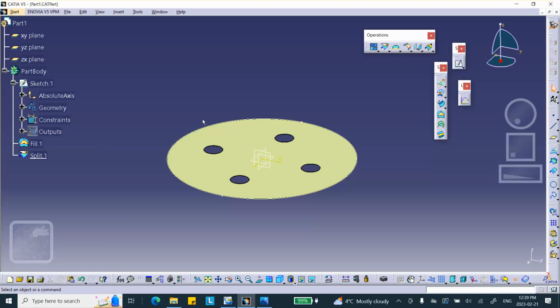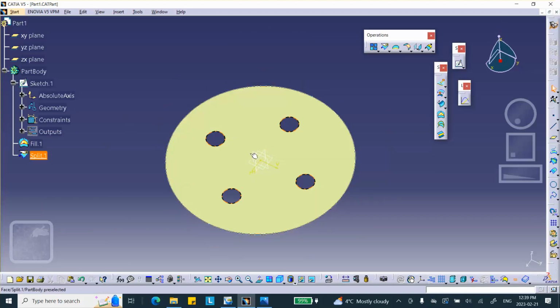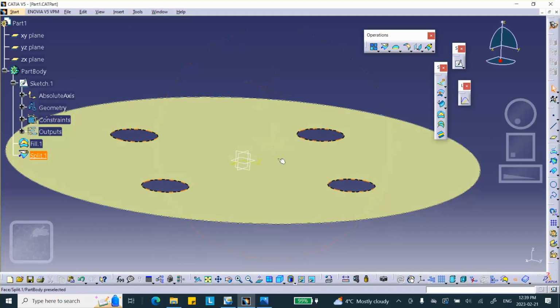Okay, good. Now I want to cut this thing and take 1/8 of that. One of the planes is obvious. It doesn't matter which one. But the other plane I need to create at 45 degrees to this, for example the YZ plane or XZ plane. So let's create that. Where is the plane? Here's a plane. There are different ways of making a plane.